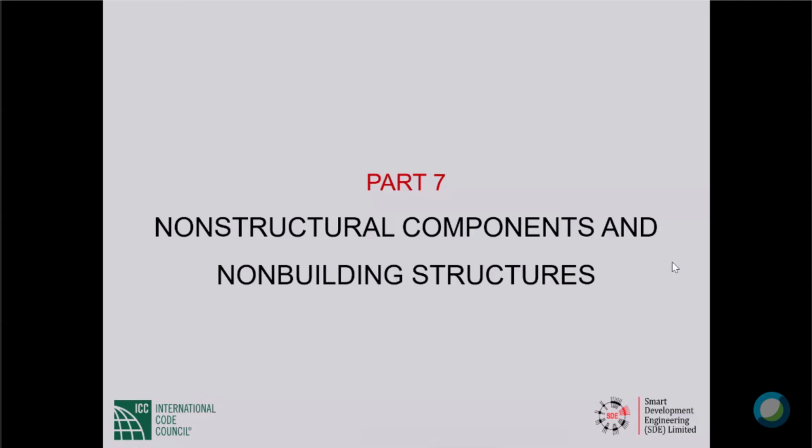In calculating the seismic deflections, remember interstory drift is deflection at level x minus deflection at level x minus 1. In calculating those, if you keep the gravity in place, that would be fine. The gravity that you should keep in place should be, I think BNBC tells you, dead plus 1/2 of the live load. Anyway, what I'm trying to tell you, it should not make any difference unless you have a distinctly unsymmetrical building. Gravity loads are not going to contribute significantly to the lateral deflections. So what load combinations is not irrelevant, but it's kind of a non-issue.